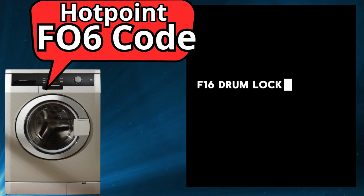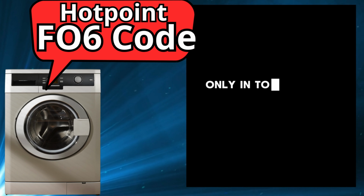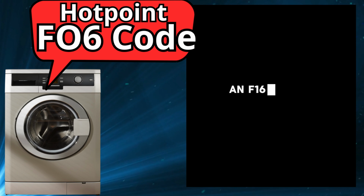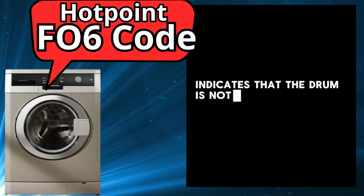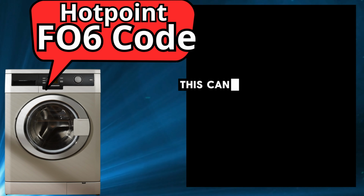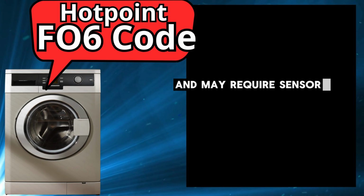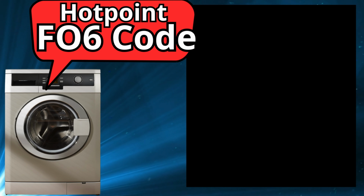F16, drum lock position sensor fault. For top-loading machines only. In top-loading washing machines, an F16 error indicates that the drum is not stopping in the correct position or is failing to lock properly. This can prevent the lid from opening or closing as expected and may require sensor recalibration or replacement.